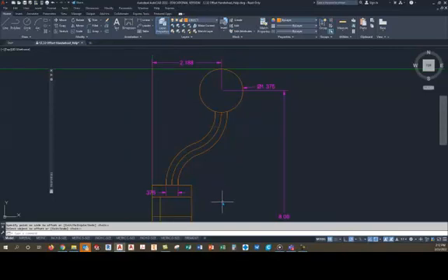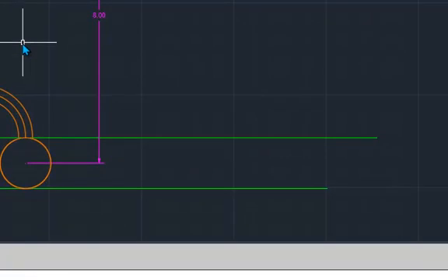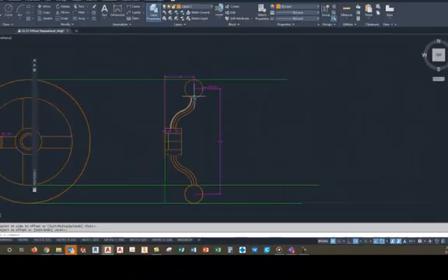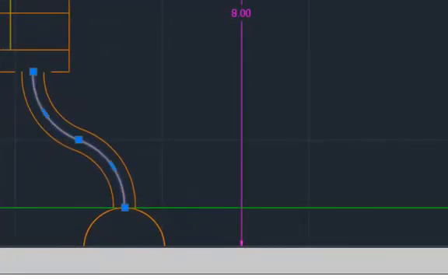And by the way, when you're sectioning this, don't go by that answer sheet that I gave you, okay? Because it does have one thing that's wrong. The wheel part does get sectioned, so you put your section lines in there. But this is a, you could call it a spoke, you can call it a web. It's not really a vane or a blade like on a fan, but those are things that we do not section. Just like when we do an assembly drawing, we don't section the fasteners.